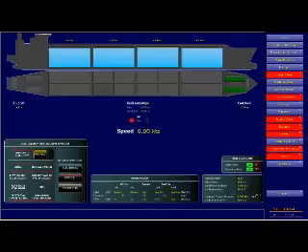So now you will start like that, and during this, of course, when a certain cargo is discharged, you will start ballasting. But try not to ballast at the early stage, because there will be stresses, and plus you will be heating the cargo from the seawater in the ballasting. These ballast tanks are not really very far away from there, so try to avoid that. The second thing you are going to do is create some gradient in the tanks. You will try to stagger the tanks.